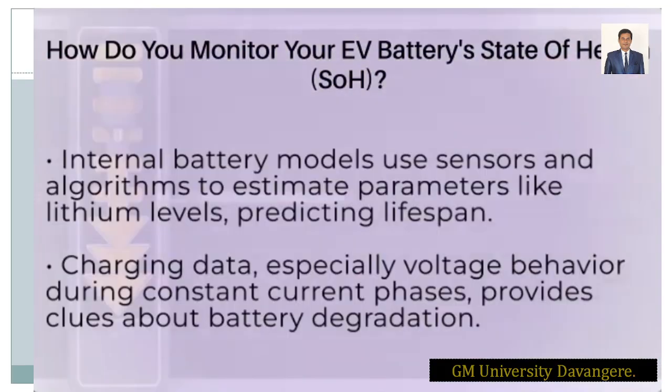All right, so next we have to monitor the internal battery modules, right? You can use sensors and various algorithms to estimate parameters like the lithium level and the prediction of the lifespan also. Think about the battery health condition, right? How it is going to charge, how it is going to discharge, and we have to see the temperature.